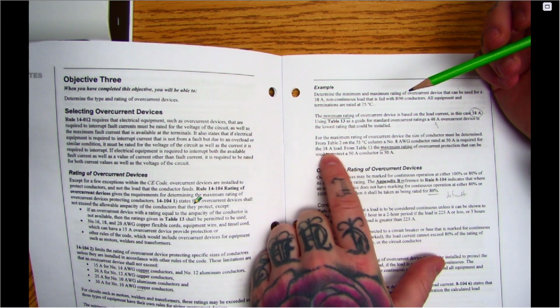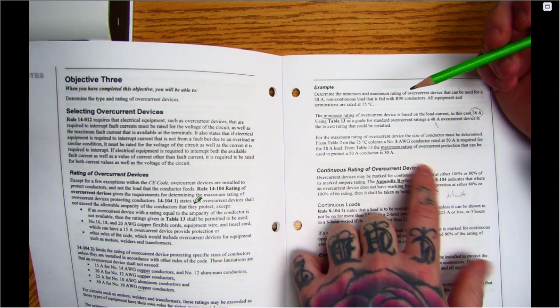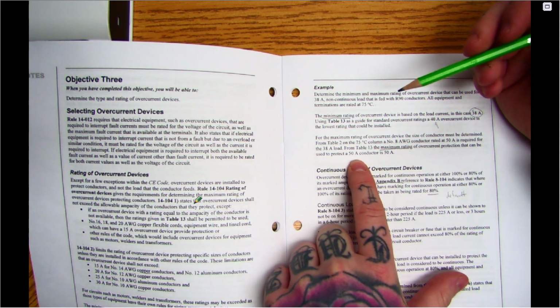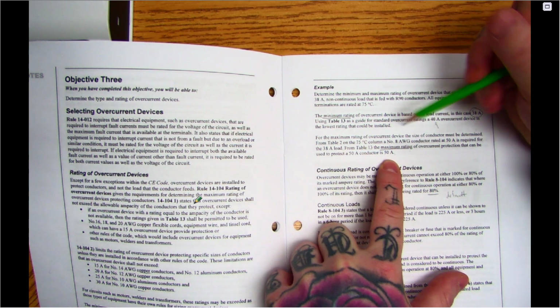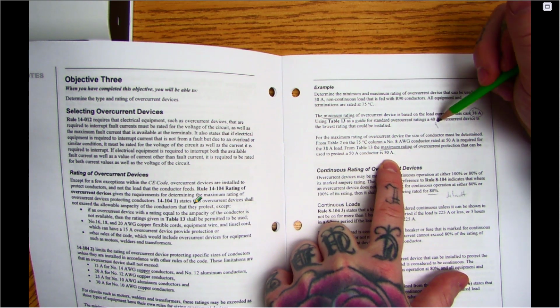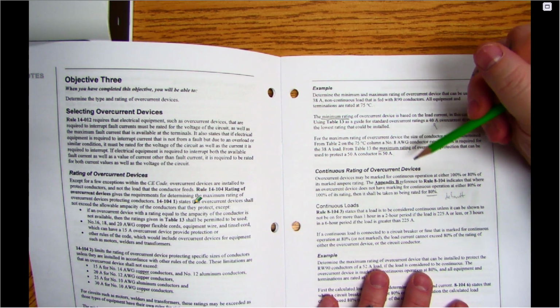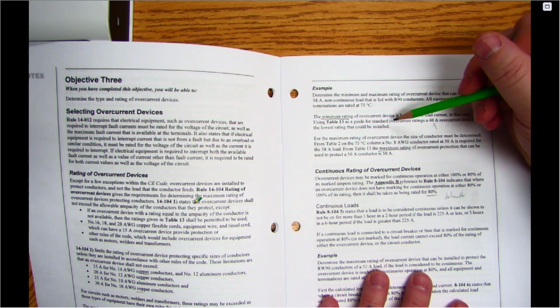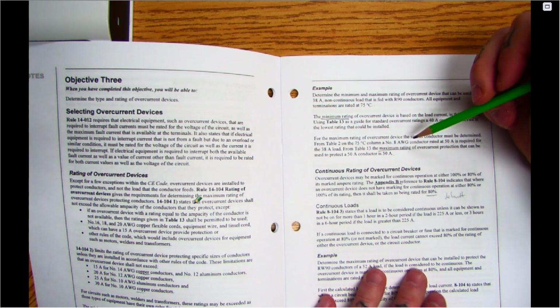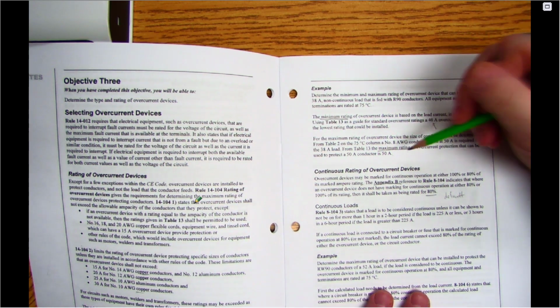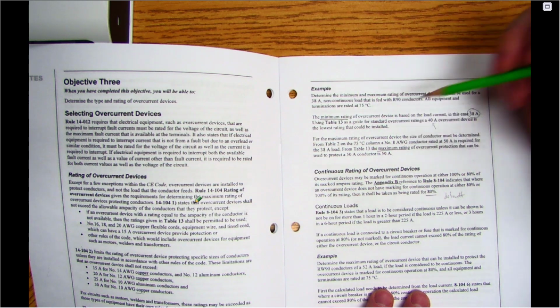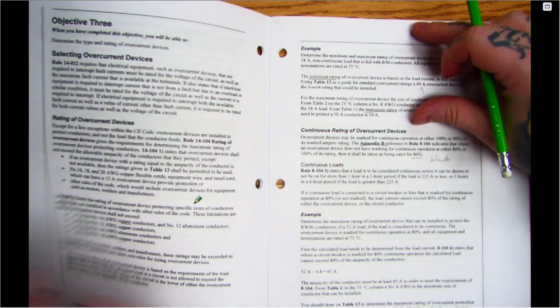Then I would go to Table 13 and pick a 50 amp. So the maximum would be a 50 amp, the minimum would be 40. Okay, so just watch the terms on that. Usually what we say is the conductor size for the load, the overcurrent size for the conductor. That's because normally we're talking about the maximum. Okay, but watch, if they do say the minimum, don't get caught on that.